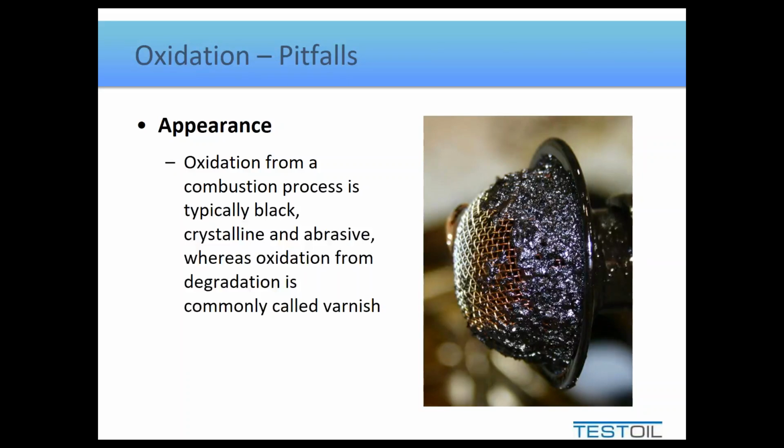The picture you see here, this is a reasonably common occurrence that happens in systems that are heavily oxidized, but basically what happens is that it plugs up the oil pickups, the suction that's driving the supply to the oil system, which in turn generally causes a decrease in the cooling capacity that the oil is providing, which conversely increases the temperature, and basically this is a self-perpetuating mechanism. So the worse it gets, the faster it gets worse, or snowball effect, whatever you want to call it.